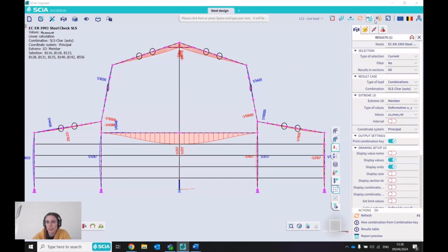You can change this in our unit settings over here. You can manage the units, and there you can choose the type of display you want for this relative unit. But I think the most practical part is to have the fraction visualization, because this at once gives information about the deflection of the respective beams and gives you an indication of how far they are from the limits.